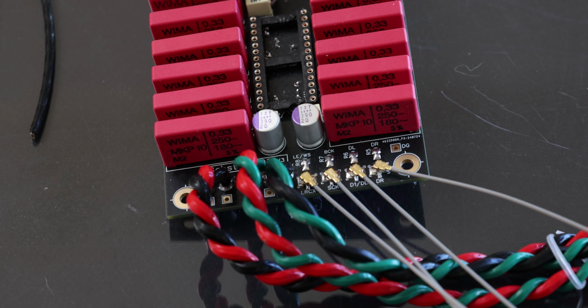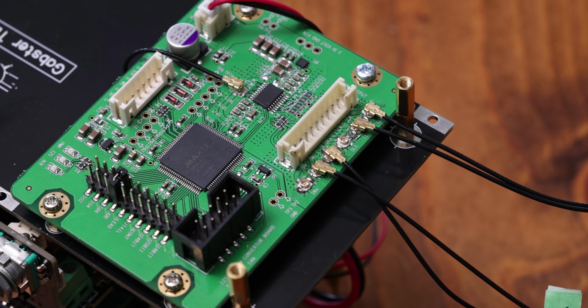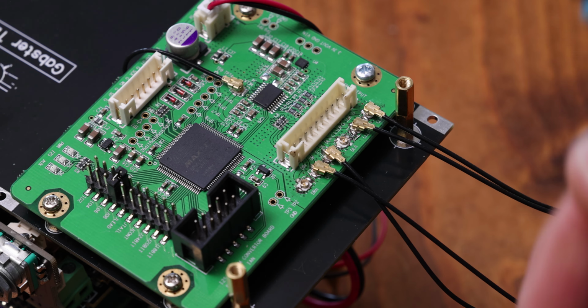Now, when you are using sim mode, this is when you need to use all 4 UFL connectors, and you're going to connect those to the PCM board. Anything with sim mode or dual or balanced differential mode, you're going to need that PCM board. So in this case, you are using 4 UFL connectors, and they're going to go to the PCM board. LRCK and SCK go to the LRCK and SCK of the PCM board, and then you get data left and data right, and that goes correspondingly to the PCM board as well.